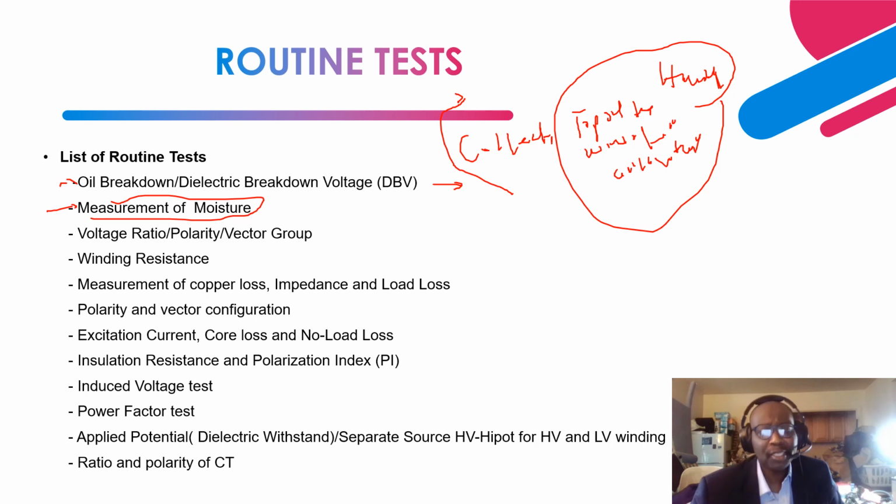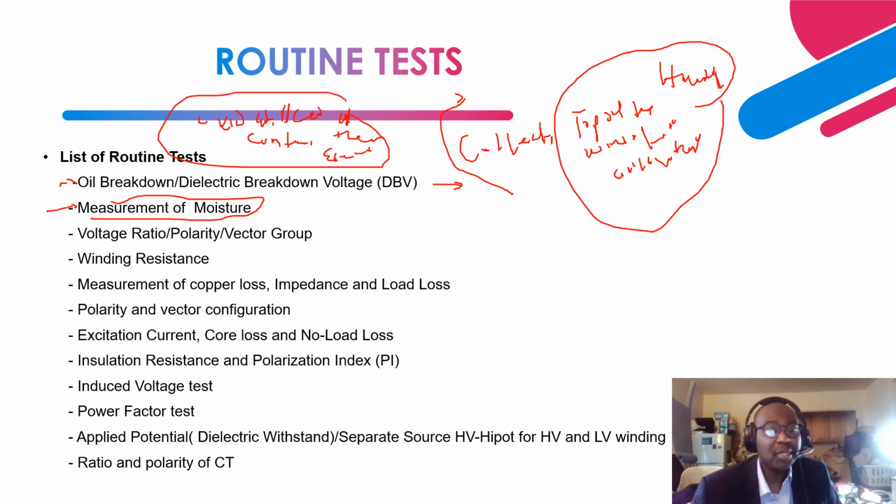During operation of a transformer that has mineral oil, due to contamination, thermal stress, electrical stress, oxidation, acidation, all based on moisture intrusion, oxygen, etc., the oil is degraded and the breakdown voltage is lowered.